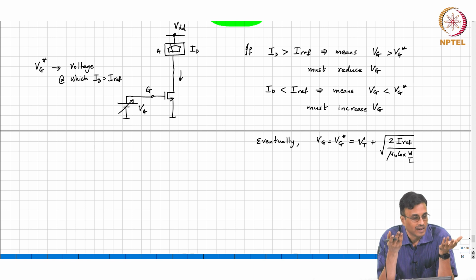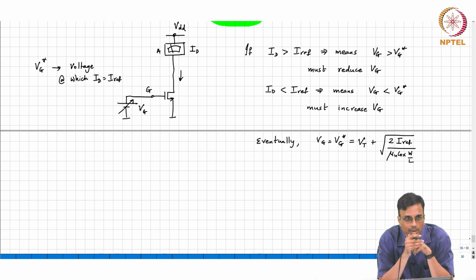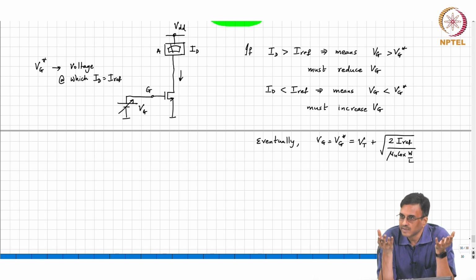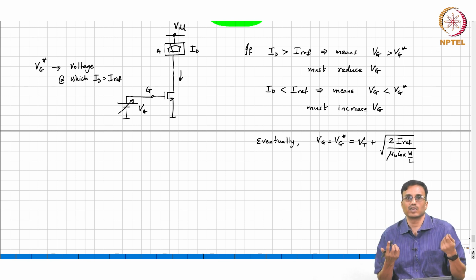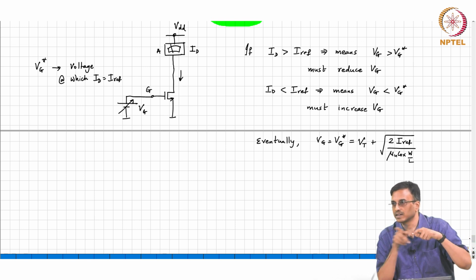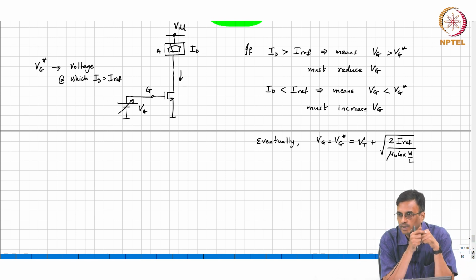It's subtraction, right? So when you compare your marks with the neighbors, you're basically saying, I got 2, he got 4, right? There's a problem. So comparison is nothing but subtraction. You want to compare currents, so you want to subtract currents. What physical principle will we use to subtract currents? God given KCL, right? So if you want to subtract 2 currents, it's very straightforward. You make the 2 currents fight, and then the difference will come out.